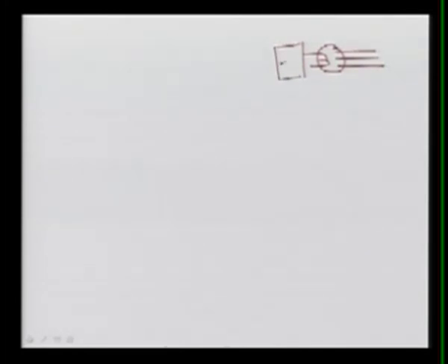your exciter, and this exciter is nothing but a 3-phase power generator, again another alternator, and the field for this we are giving from here, this is a field, and this field current is coming through your amplifier. If you remember, this was nothing but your change in VR here, and this field is for your generator or alternator, where the 3-phase power supply is going.